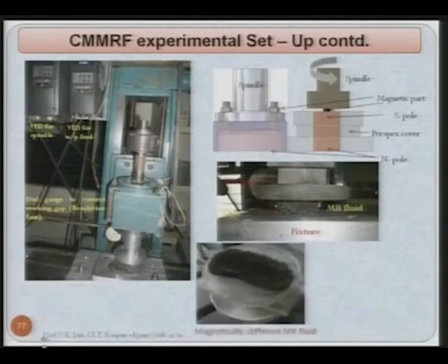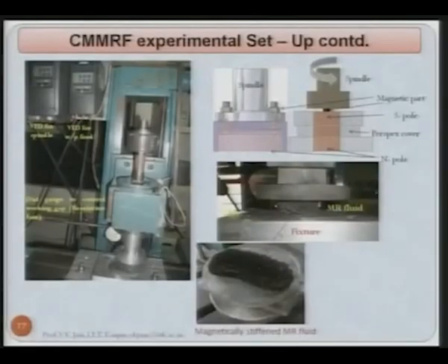Now, initially there is a magnet actually which is, this is the top part which is shown, but if you see from the bottom then this top part and this part will be visible like this, and this is nothing but this particular part. So, here before really finishing start, this forms the brush as the brush shown over here, and when you rotate this magnet then this brush is responsible for removing the peaks from the workpiece surface and shearing off the peaks and improving the surface roughness.